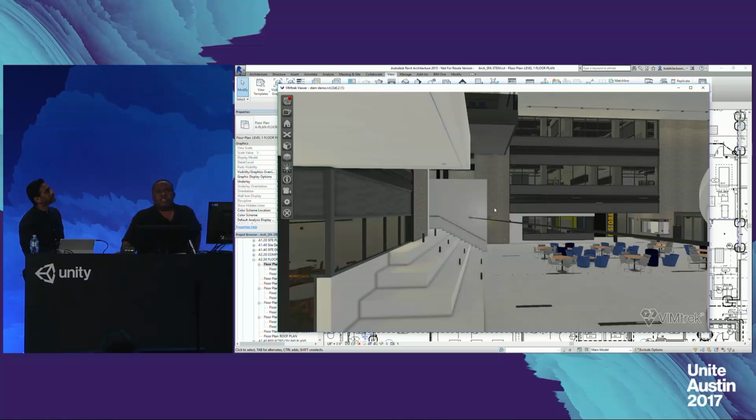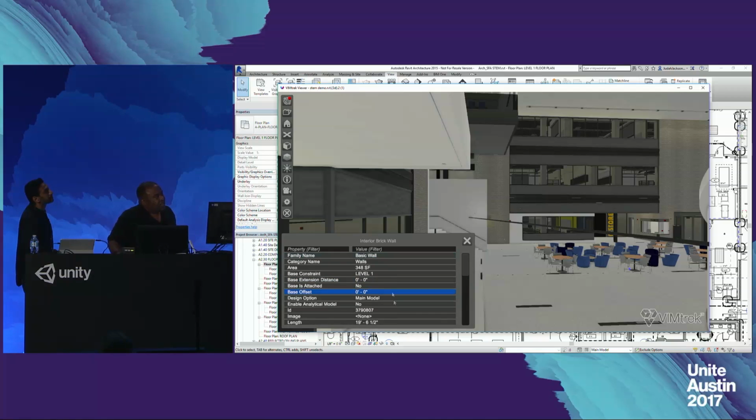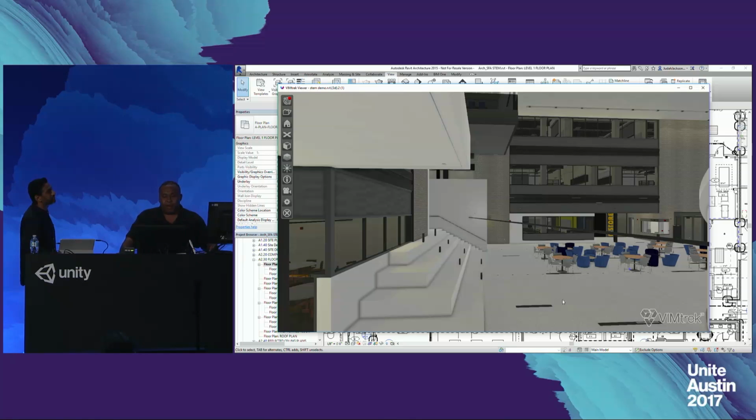what you're looking for is things that look out of place inside a model. Those subtle things that come to your mind as you're walking through the model can save you thousands of dollars on the project. Like, what in the world is this sticking out here at about eye level going down the stairs? Well, this model actually combines the architectural with the mechanical, electrical, and plumbing files, and allows us to see the data that's underneath this particular object, so that we can actually click on the object, there we go, and see that we've got an underground conduit that isn't exactly underground.